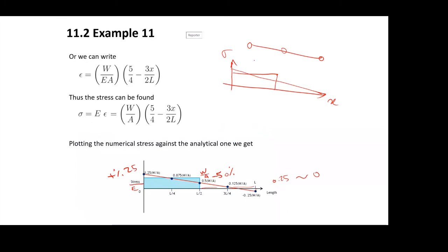See, if you look into this case, it's trying to fit a line to a step function. Now, instead of doing that, think about using two quadratic elements. So one element here and the other element here. And then the first element, the line function, is going to try and fit the first half. And this is basically constant if you consider it this way. And the other half is also constant, it is 0, but it is constant.